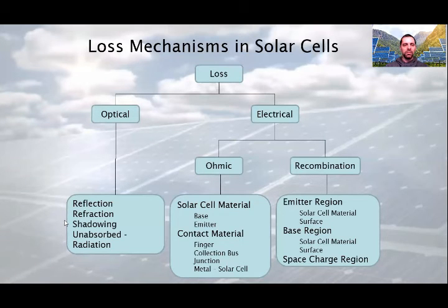The ohmic losses include electrical resistance to transport of charged carriers within doped regions of the device, emitter and base, resistance of a p-n junction, a contact resistance on the borders of the semiconductor and metal collectors, and the resistance of thin metal films of the collector system.